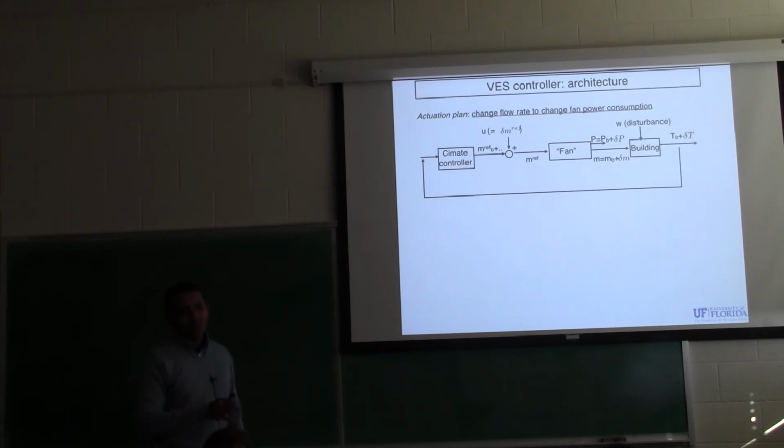and add this signal. Now we are actually not going to go with a wire cutter and actually cut the wire. We'll do all this remotely through the internet. So in building automation systems, there's a separate communication protocol for sending these commands, and you can send commands with higher or lower priority. So the software that Tim Middlecoop wrote allows you to change the priority of this signal. We take whatever the building automation system is doing, add numbers, change the priority, send it to the fan controller, and it does that. Right? So it's equivalent to going in there and cutting the wire.